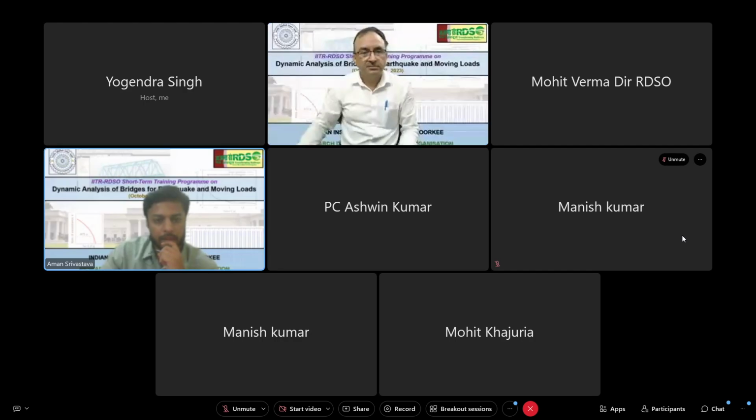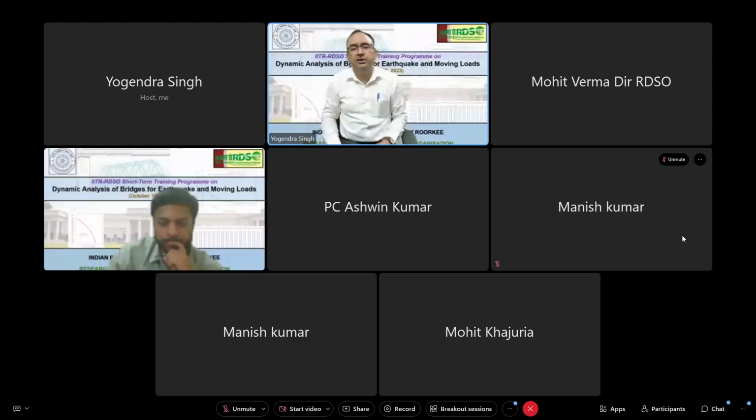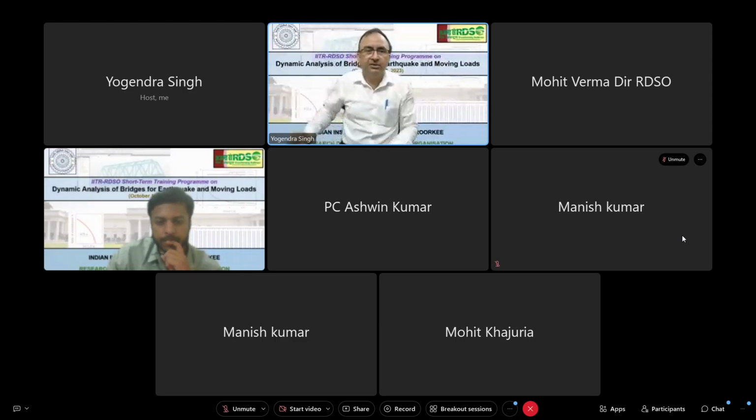Sure, sir. Mr. Jay wants to ask, for soil, generally we are considering linear springs in seismic analysis without damping constants. To what extent will modeling the damping constants of soil be helpful in reducing seismic forces in the bridge? Not much, because even when you are considering soil as deformable, most of the deformation is occurring in the superstructure. So even when you consider damping of the soil, it is not going to cause much effect. So that's why in many cases we ignore it. You will not get much advantage from that.